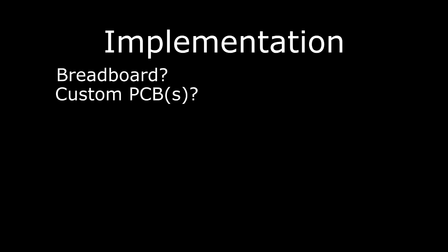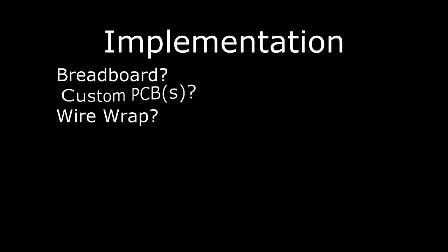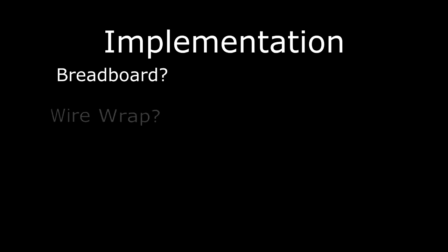And then there's the issue of how to actually implement it. Is it on a breadboard? Should I design a PC board or multiple PC boards for it? Should I do wire wrap? And so on. In this case, because it's a one-off thing, it doesn't really make sense to design a PC board. That would get quite expensive. I think I've had enough of wire wrap in my day. And the large number of chips kind of rules out the little plug board type implementation.